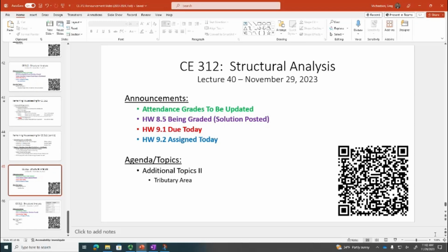What was this? wL squared over 8. Good, because we're going to use that today. That was the maximum moment due to a uniformly distributed load put on a simply supported beam. The formula that I had you derive was the most ubiquitous one, period, in structural analysis.